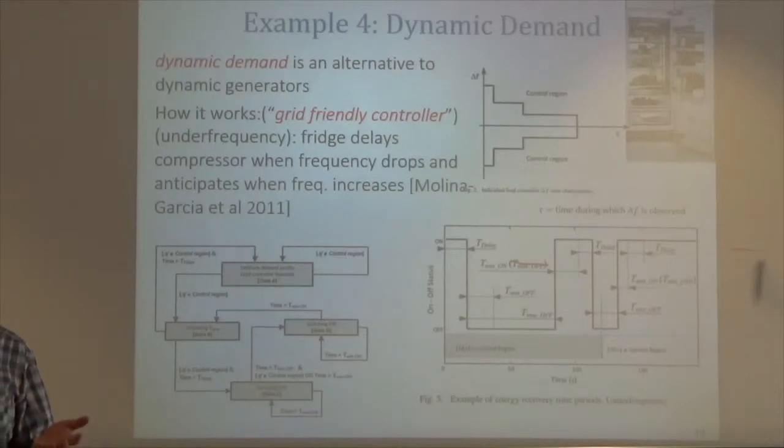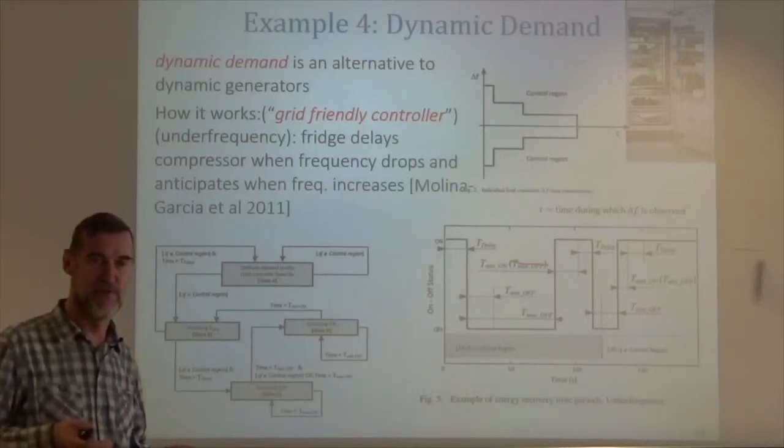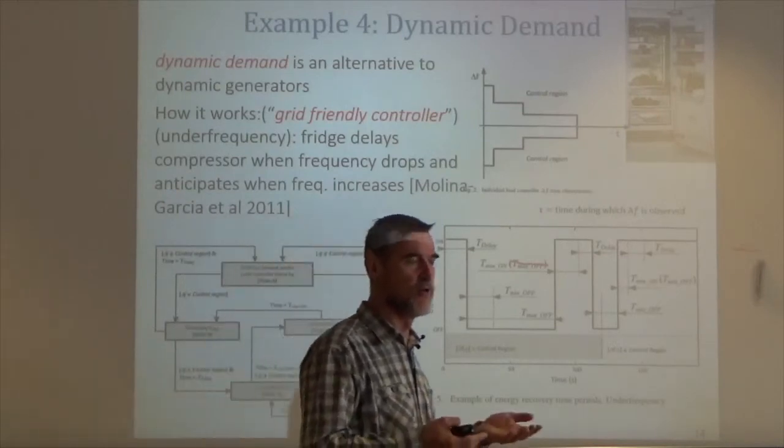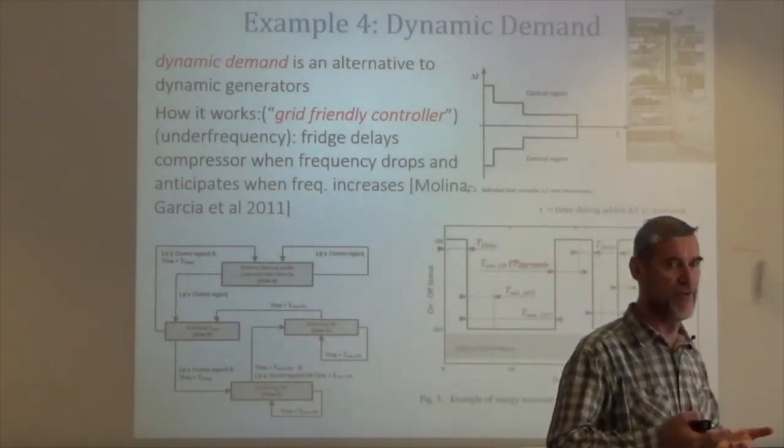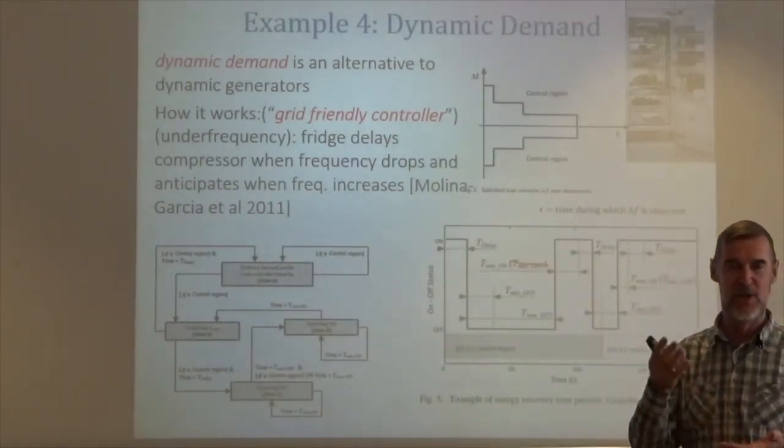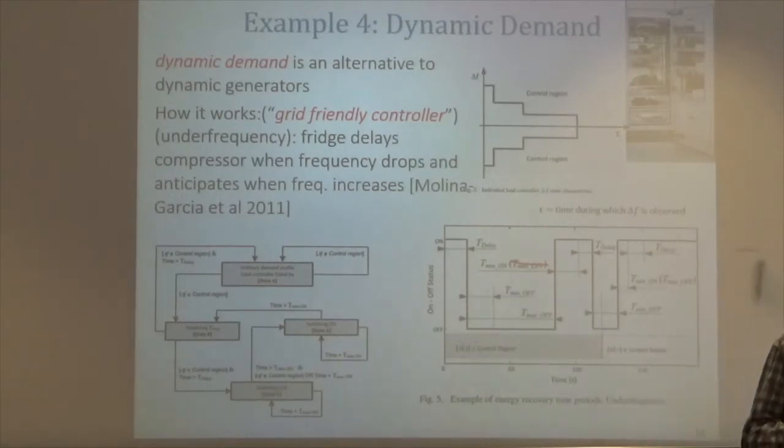So a large country has millions of fridges. That's a fleet that you can control. Statistically, out of the million fridges, if you install a demand response system into them, then half of them would be between 2 and 3 degrees, for example, if they are constantly oscillating between 2 and 4, which means that half of them could respond to a demand response event.